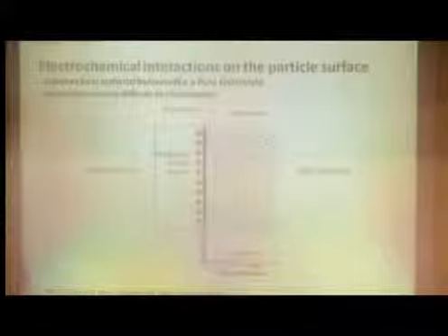What else would we expect to happen then when we put in nanoparticles? Well, this is taken from a paper by John Lewis, which he published in 2004. He was actually, about 10 years before that, he published a paper talking about what might happen if we used nano dielectrics. And I don't know, that was probably the first paper in this particular subject area. He assumed that the host material might behave a little bit like a fluid electrolyte, really.